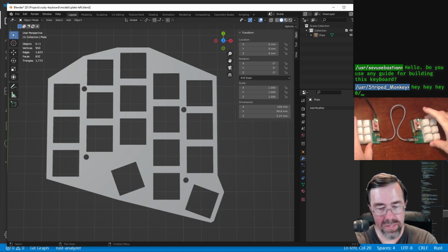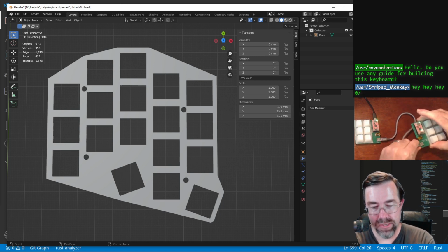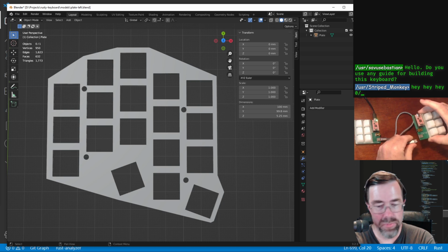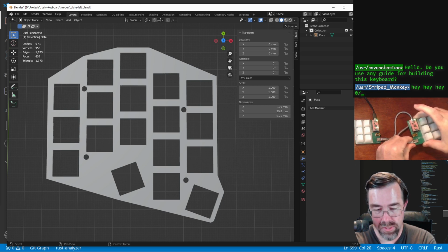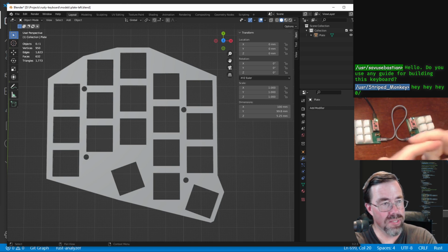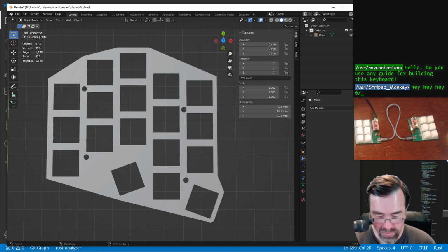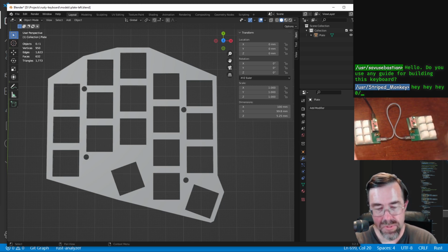From this proto board, I can connect either way, and I settled on USB-C because as long as I can get it soldered correctly, it's a nicer connection because I can do something like this and not worry about shorting the power to ground. Whereas with the audio connector, you have power and ground sliding past each other potentially, and they can cause problems, right? You're not supposed to unplug it while it's electrically connected. So other than examples and other boards and what people have said on posts, I really don't have any other kind of guide.